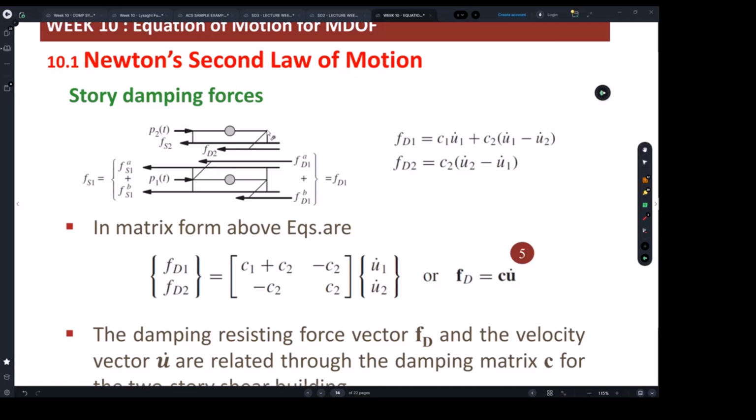Yes. So we're gonna find the velocity at this floor and take away from it the velocity at the lower floor, because there is a case or a stage where both of the floors are moving together. When both floors are moving together, it's gonna give you no stiffness, it's gonna give you no damping force. That's basically why we have to do these kind of things.